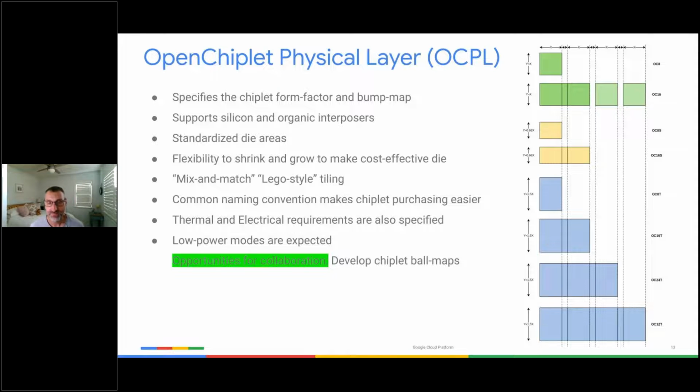Yeah, the STAR program from TSMC, as I understand it, I've only seen some information, stands for standard architecture. As opposed to providing a technology that you can use any way you want to assemble your own fantastical set of chips and arrangements, they've come up with about 6 layouts, like a chip in the middle and 4 HBMs at each corner, and another variant. They provide these as standardized configurations that have some level of verification, or at least feasibility from a thermal and manufacturing point of view. So you pick option A, B, C, or D rather than making up something on the fly.